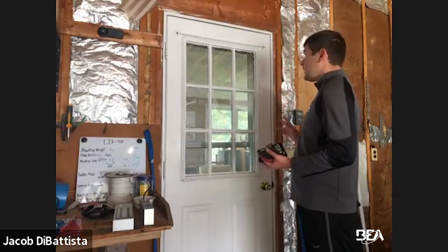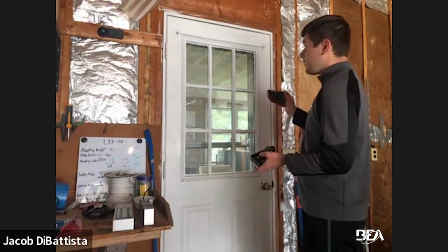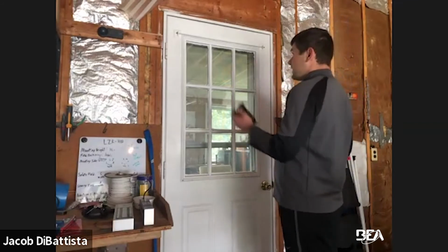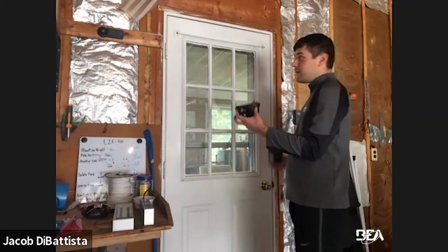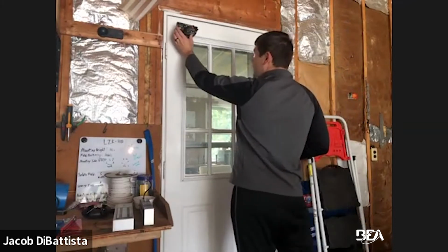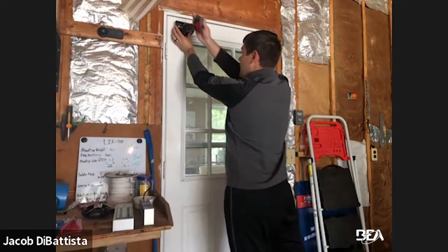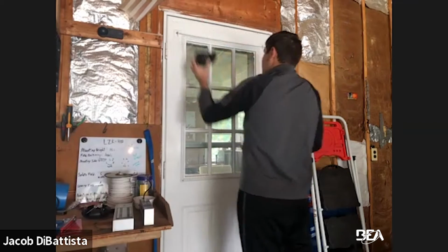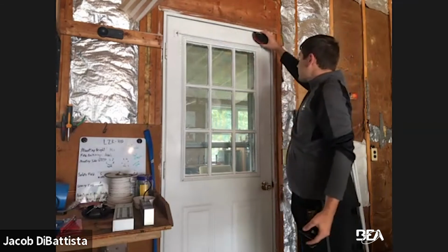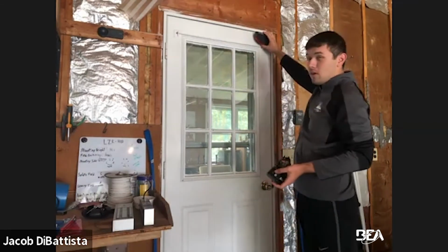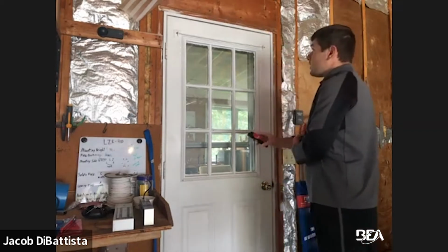Let's act like this is a regular automatic door for pedestrians. Usually, when you're deciding which sensor to put up on the door, which side is the hinge on, the left or the right? It's on the left this time. So I have a left mount FLATSCAN 3D that usually you would mount up on the top left corner of the door, just like this, making sure that the top is horizontal at the top and the side is completely vertical with the hinge side. If it was a right mount sensor and the hinge was on the right side, same concept. Just make sure that the arm of the door is not in the field of the sensor. Make sure you have a spacer or whatever behind it to make sure it goes out past the handle.